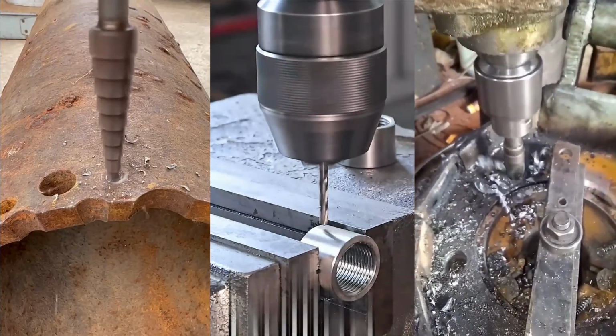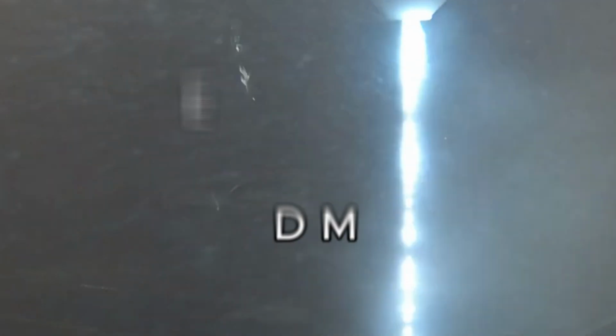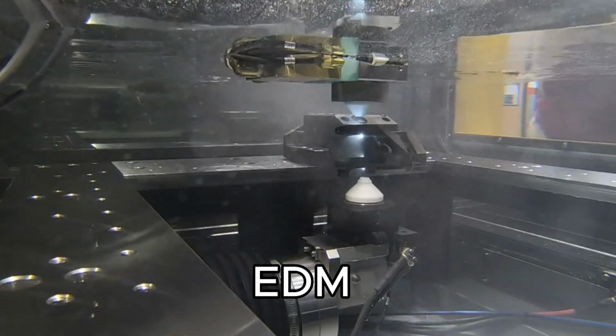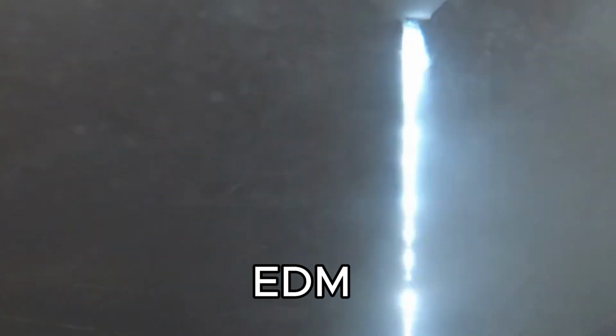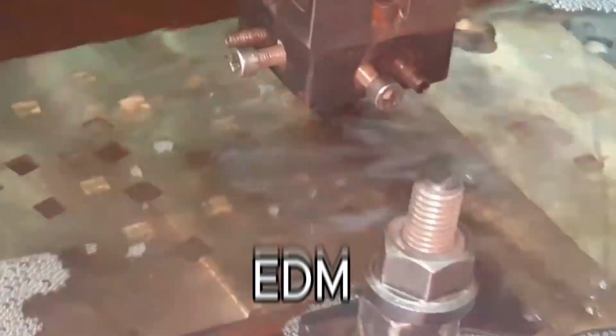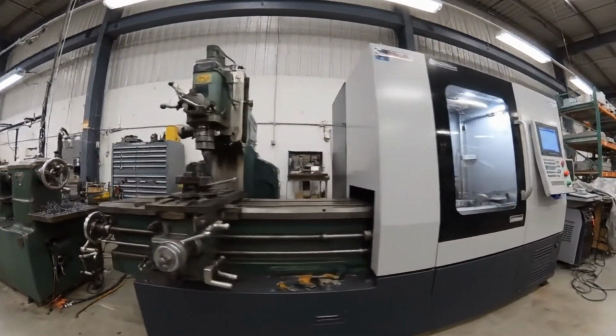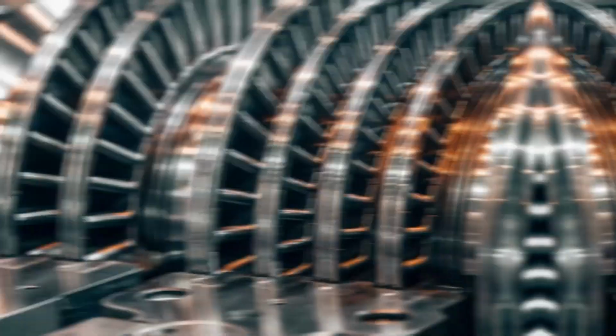Other advanced techniques include grinding, for high-precision finishing, and EDM, or electrical discharge machining, which removes material using electrical sparks. EDM is used when materials are too hard or complex to machine traditionally. Thanks to modern CNC machines, all of these processes can be automated, achieving extreme precision, repeatability, and even making parts overnight. Whether you're building a turbine blade or a smartphone mold, machining is where precision begins.